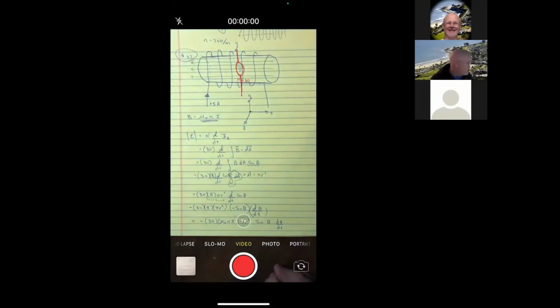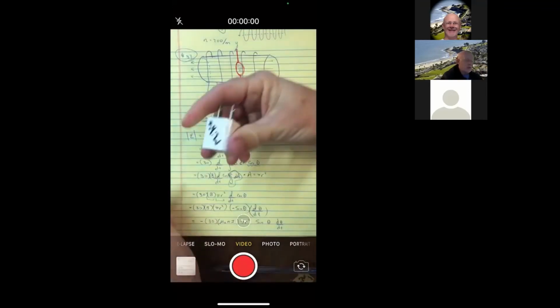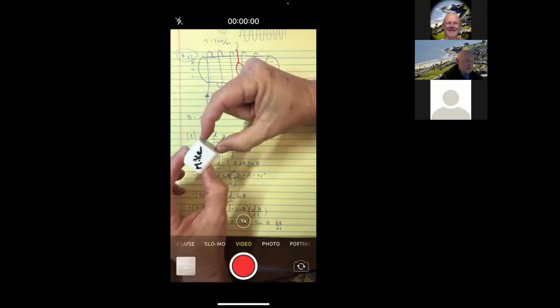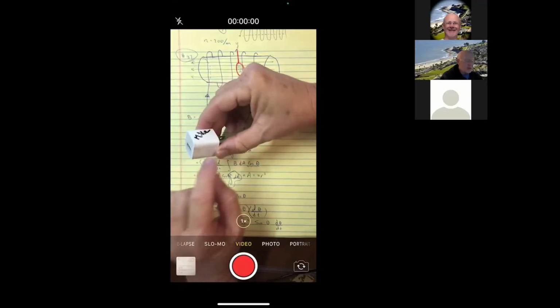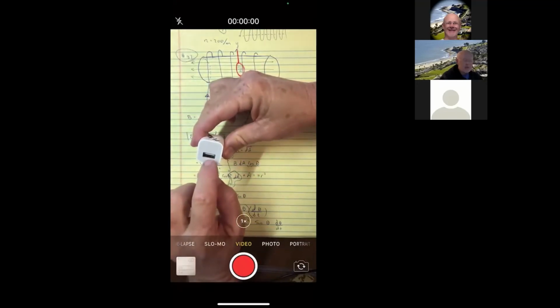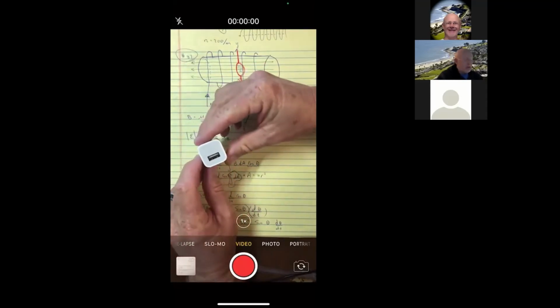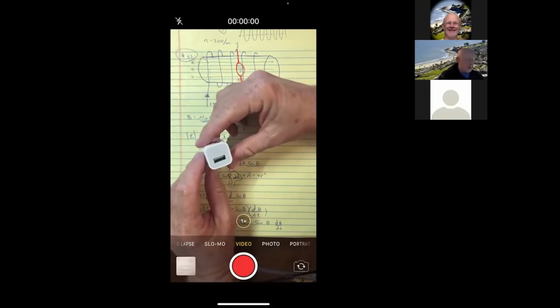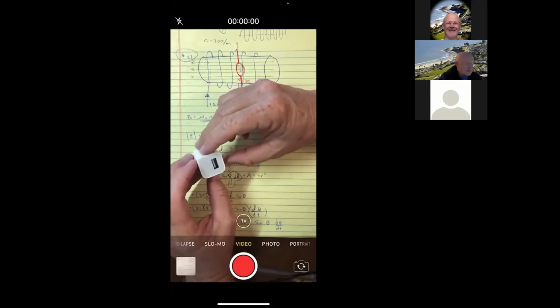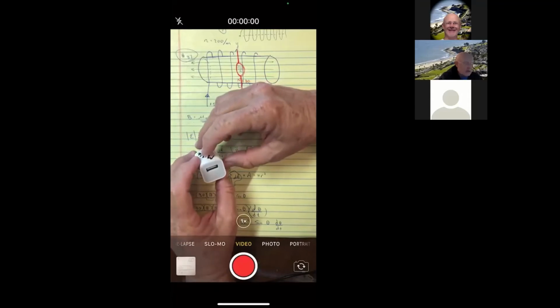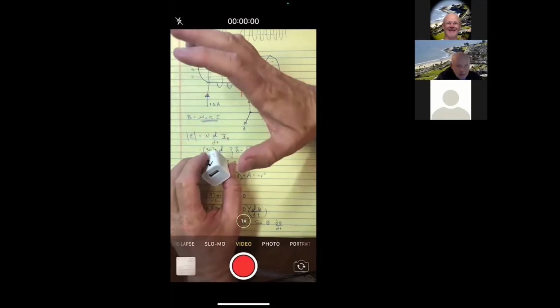which is why you need those little cubes that look like this to plug in your phone. You're plugging this into the wall, which makes voltages back and forth, AC, and eventually through a little bit of electronics in here, it comes out this end in a constant one direction. That's how batteries are DC. Batteries are the simplest ones to talk about, which is why that's all we've talked about so far. We're just now getting to the point that we're ready to shift gears away from batteries and start talking about electricity that is generated from generators.